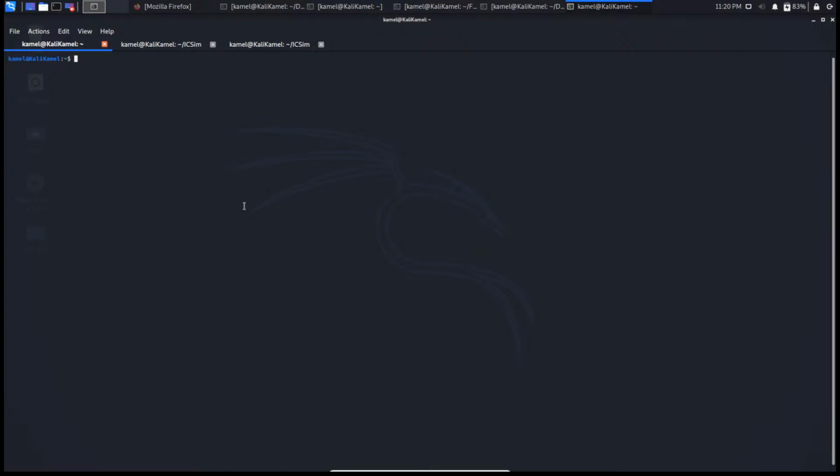So I'm going to go ahead and clear my screen. And the first thing we're going to do is look at some CAN data. So let's run candump vcan0. candump is a program that outputs CAN bus data to the standard output, or in layman's terms, your screen. Your monitor, your terminal, will then show CAN data. So I'm going to hit this, and nothing really happens. And there's a good reason for this. It's because there's no processes sending CAN data onto the virtual CAN interface.